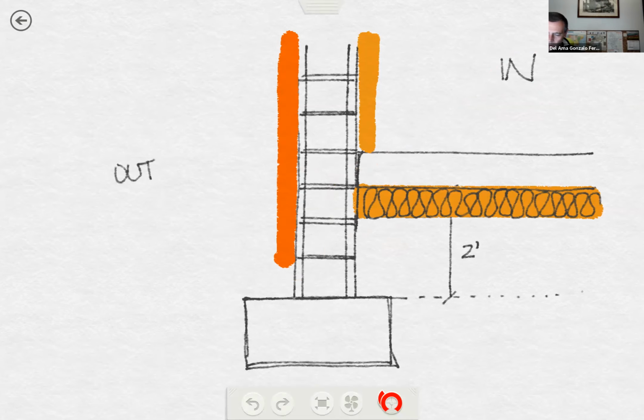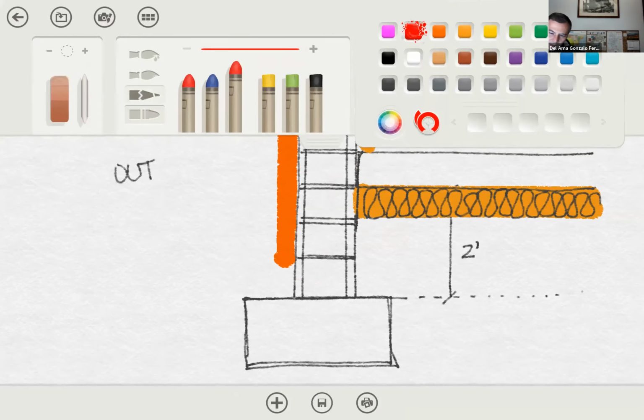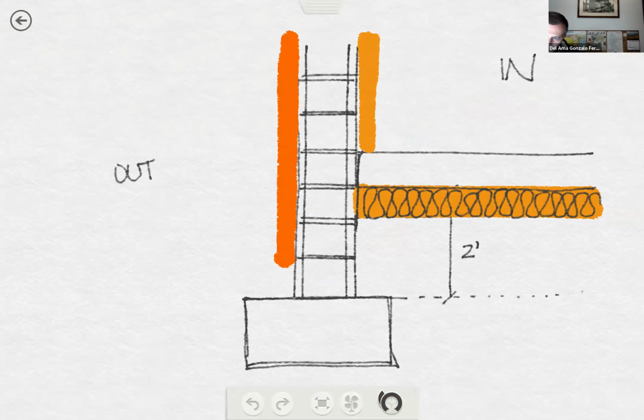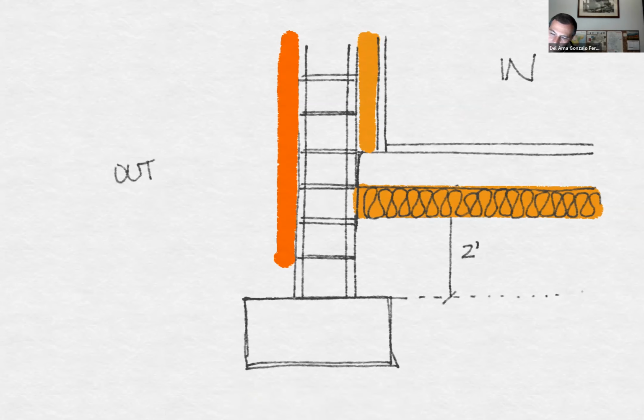But this is the thermal insulation, and we can't see this. We can't have the thermal insulation exposed. For sure, I would need the gypsum wall here, and here I would need a layer for the flooring. Okay.